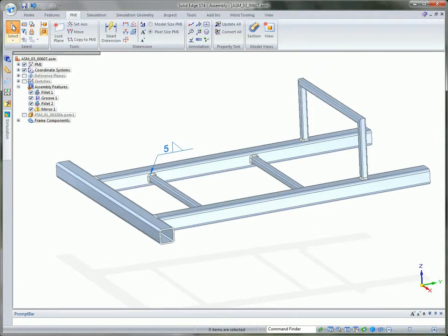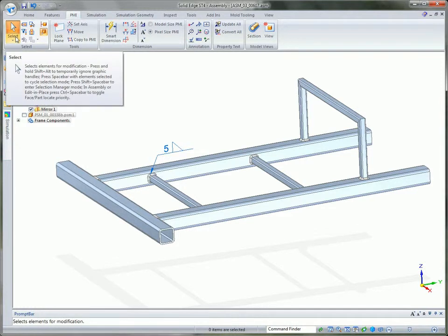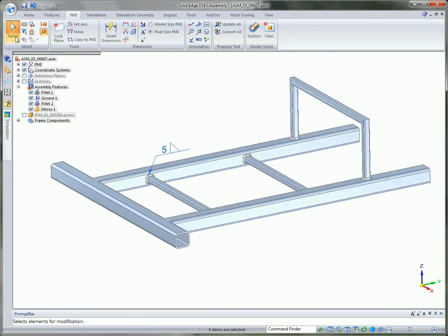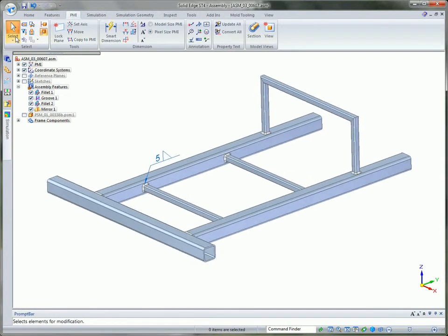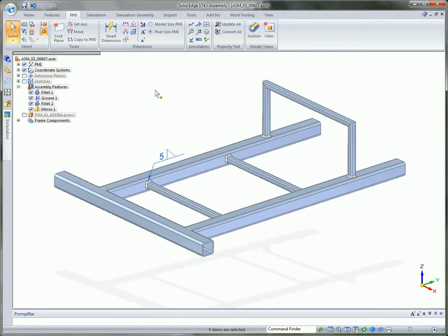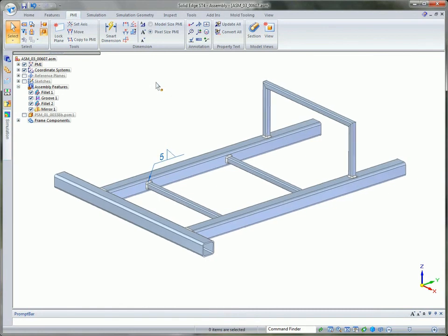So, with Solid Edge ST4, users really do have the flexibility to define and create any number of structural frame styles and sizes in a streamlined workflow, and then are able to take that same design into the weldment environment, where they can apply weld beads to all the frame connections. And then of course you don't want to forget that we've added the beam analysis in ST4. So with that, this hopefully gives you a good overview of frames, beam analysis, and the weldment environment.